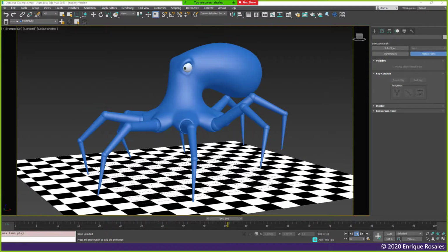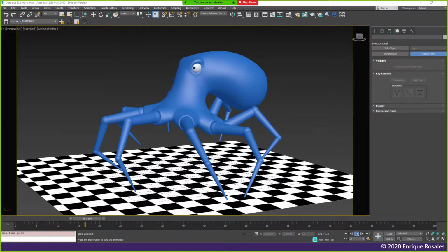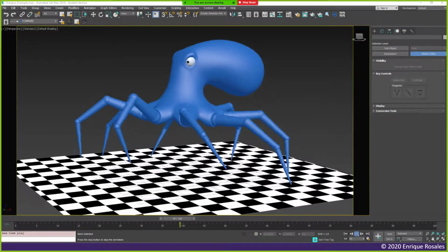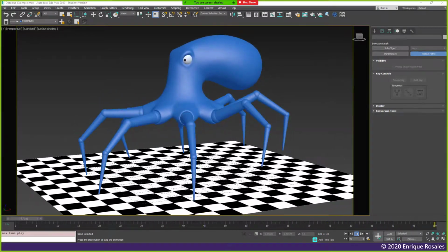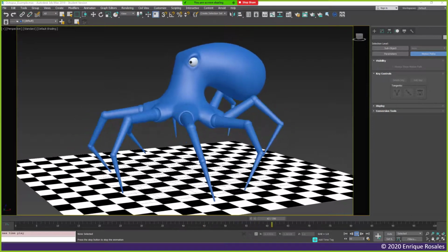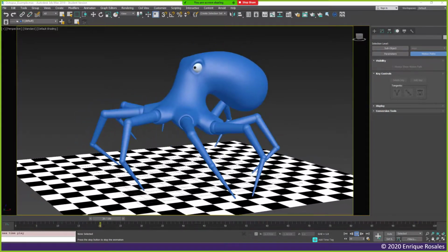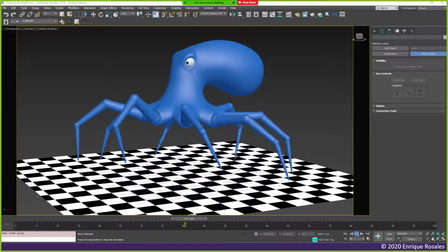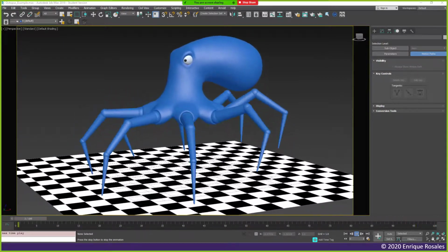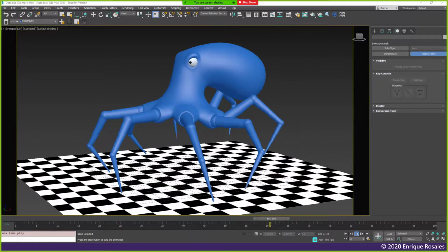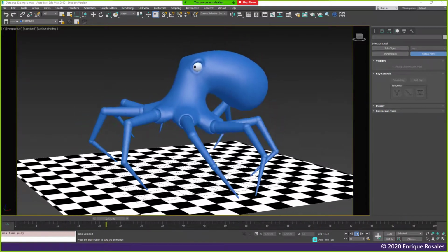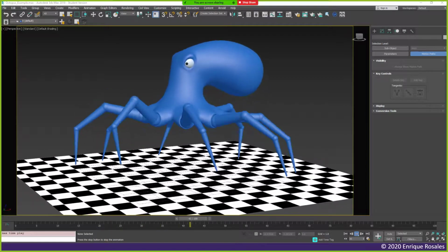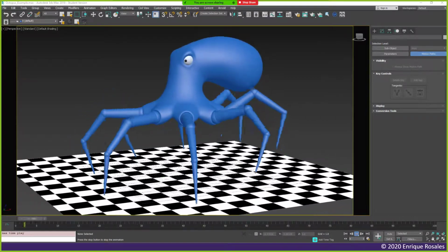So I see in the chat the math of the circle-circle intersection is not entirely intuitive. So just to check the concepts for sure: IK is nothing but an optimization problem where you solve for the transformation matrix given the untransformed coordinate and the transformed coordinate, right? And yes, a circle-circle intersection is just an instance of an analytical solution for solving for that transformation matrix.